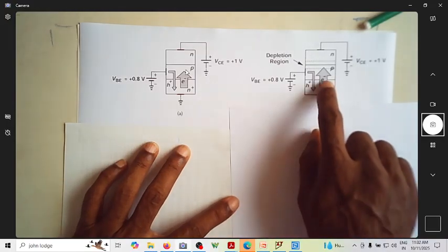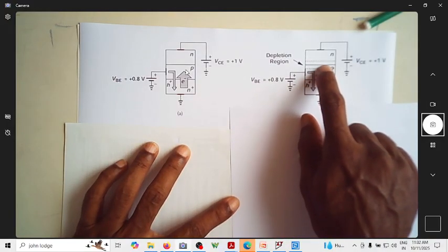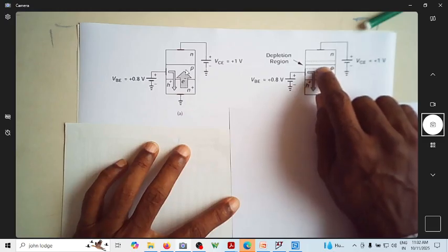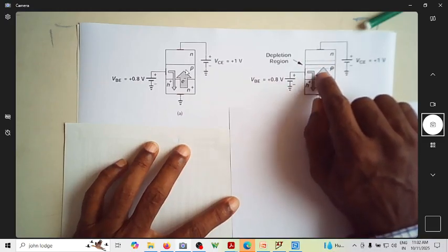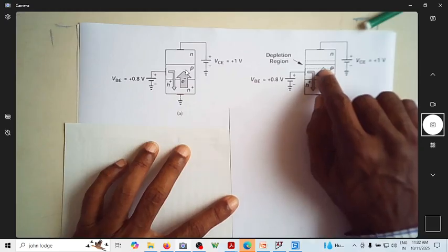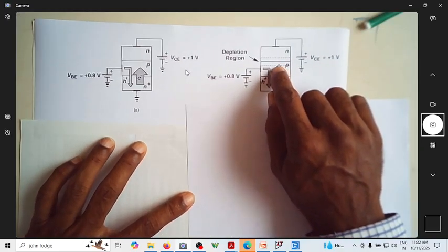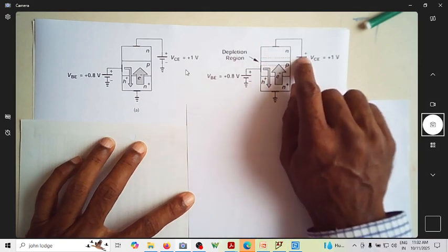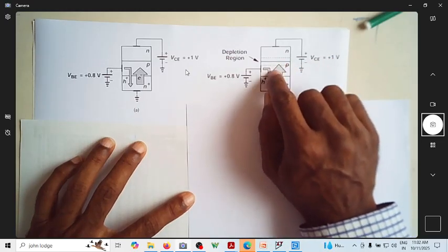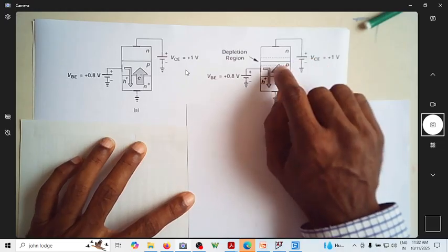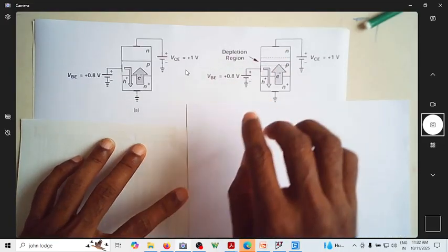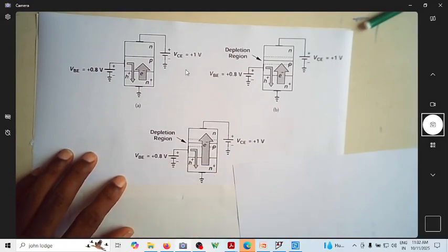what happens is, can you see, this is penetrating into this. Since you have positive voltage, these electrons will be crossing this depletion region. Because there is an attraction here and a huge number of electrons are coming, these electrons will be moving towards the collector terminal, because they have a huge attraction, the recombination is also very low, and this area is also very thin. So the electrons are trying to cross the depletion region. That's what happened here. Can you see?